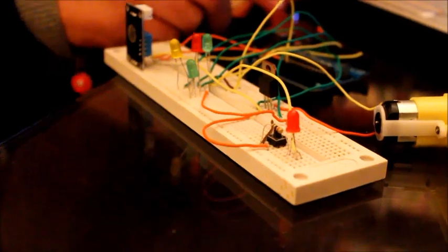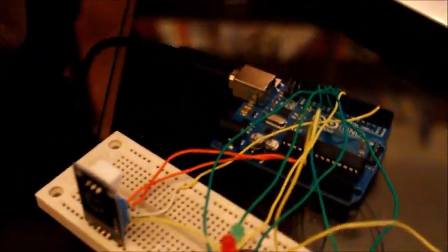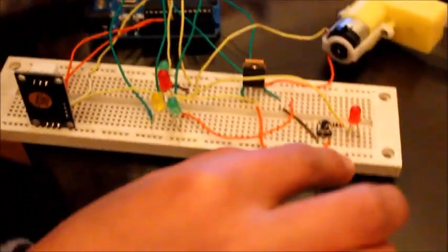And it goes off. Okay, so the third function of our fan is the swivel, which is the cover of the fan, which rotates to distribute the air in different directions. So we made a button connected. One side of it is connected to 5 volts, and the other side is connected to pin 13, which is our output. And then we connected a resistor to pin 13 in order to decrease the voltage.